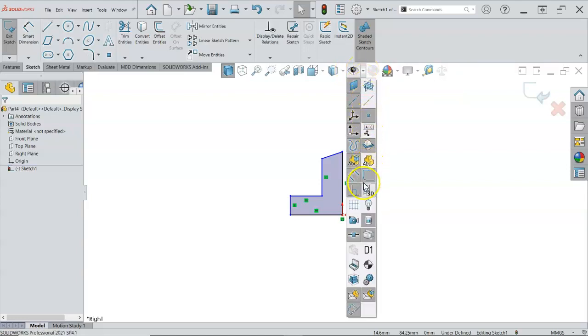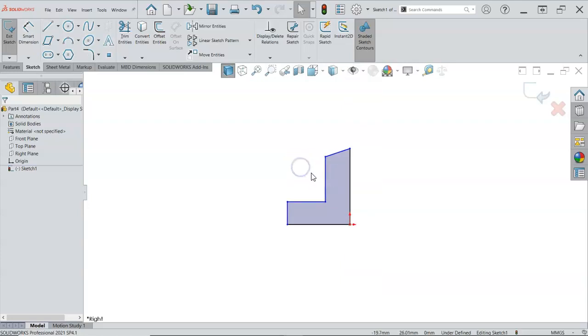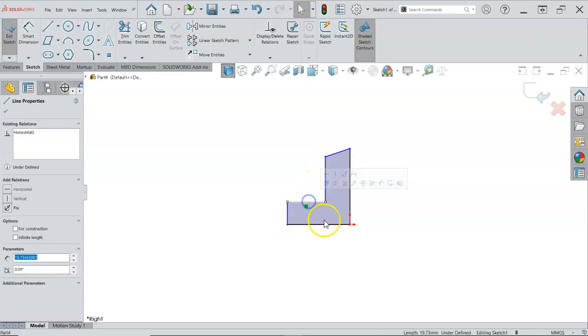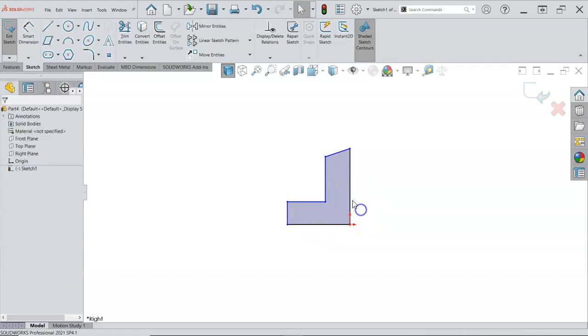So clicking the little down arrow will come about halfway down to view sketch relations and turn those off. So rather than having them always on, just the objects that I select are going to show me the coincident, the horizontal, the coincident, and the vertical.